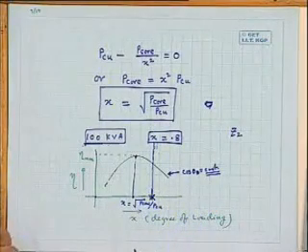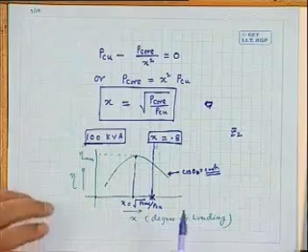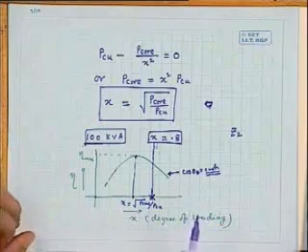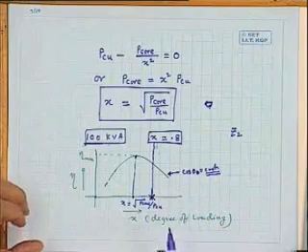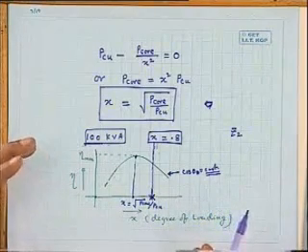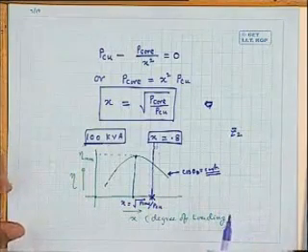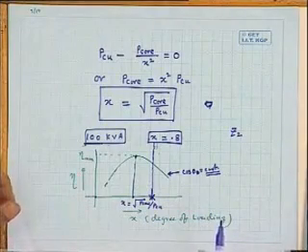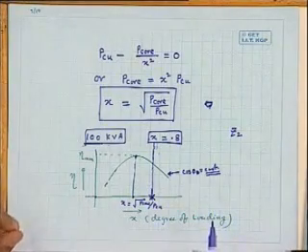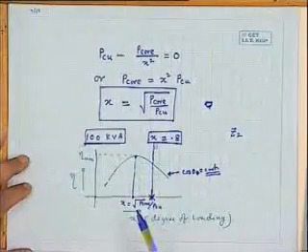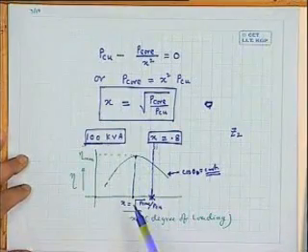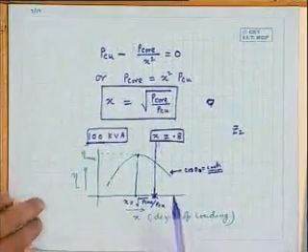Generally, suppose you are given a choice of what value of X you would like to have. Suppose a transformer is 100 kVA. Why have I purchased a 100 kVA transformer? I must see that it is operated at its full rating. That's why the 100 kVA transformer has been purchased. So what will be your choice of the value of X? You would like to have 1. If X is 1 and the transformer is operated to its full capacity round the clock, then you will get the highest efficiency possible. Are you getting?